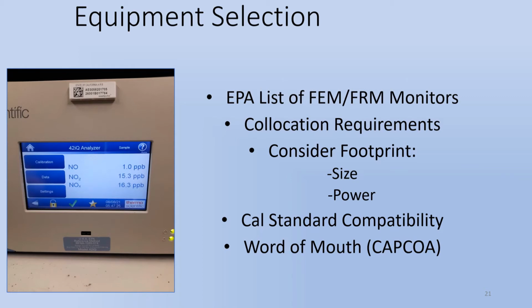Now, new technology in monitors is great, but remember, per the CFR, within a PQAO, 15% of primary monitors of each method must be co-located. So if no one else is using it yet, you might be deploying two. Similarly, you need to ensure that your calibration standards work with your new monitors, or you will be adding to your procurement list. Asking around is a great resource, and there are opportunities within our community to do so. I've even gone so far as to ask a manufacturer for references and spoken with out-of-state agencies before for their impressions and experiences.